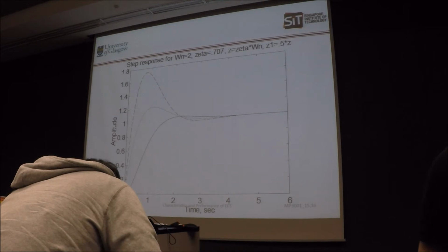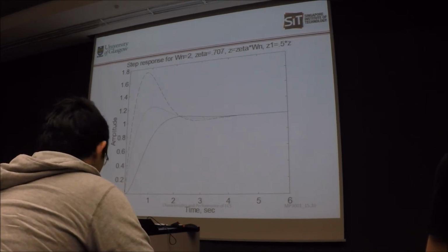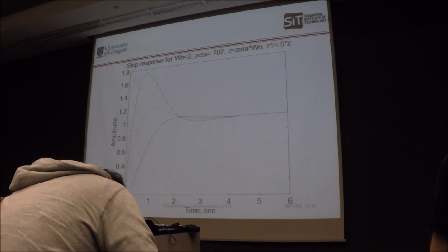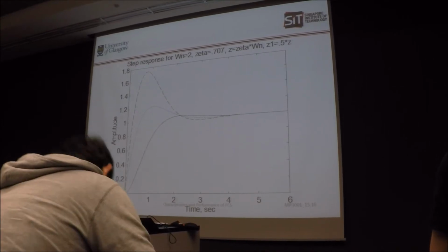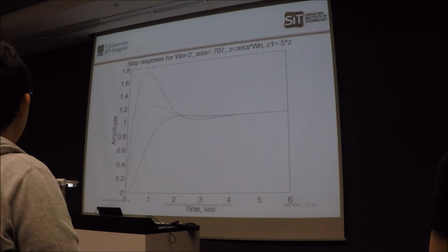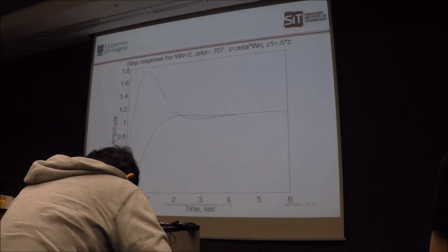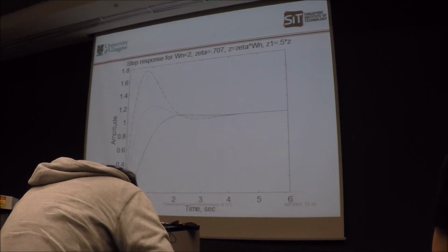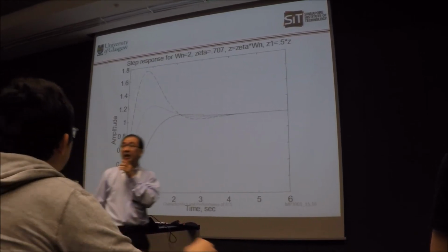We mentioned many times that your D controller is good because it has an anticipatory effect and improves your relative stability. But all this effect only comes in during the transient. The moment it hits steady state, there is no more effect. The effect diminishes after the transient has decayed.